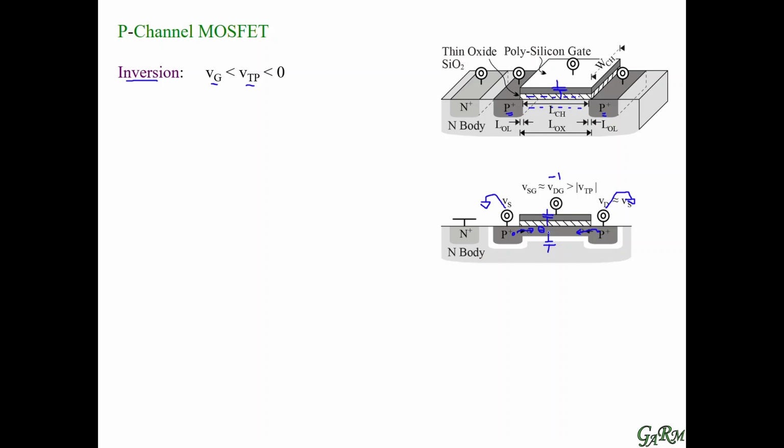That negative voltage is so high that it basically populates that entire middle region. And what we've done here is that now we have a region between these two P plus regions. We've connected them with effectively a P-type region here. And we've inverted a channel, because before we had no channel. This is N-type, but now we've made that region P-type, so we've inverted a channel that connects those two P plus diffusions, and it went from N to P, so that's an inversion.